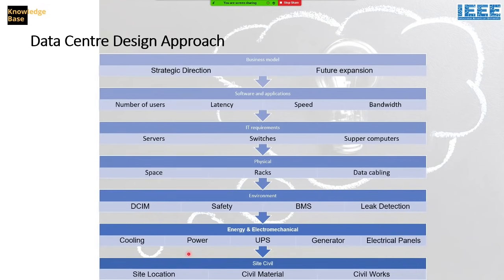So yeah, just a point on the site location and its importance. The requirements state that you cannot build a data center, let's say, close to an area where there are floods, because if there is a flood and the water comes inside, you will have an issue. If you're building a data center, it's always recommended to put it on the second floor, let's say, of the building. So there are many requirements depending on the location and the site, and also the temperature of the location or the area you're building the data center in plays an important role in the data center's efficiency and operation.